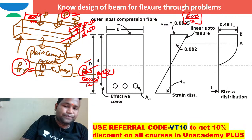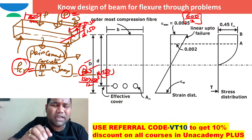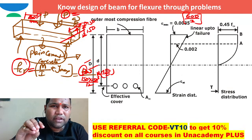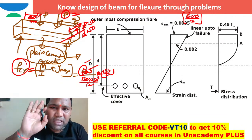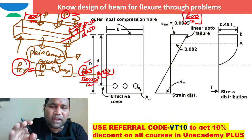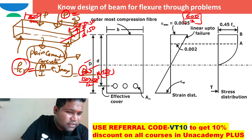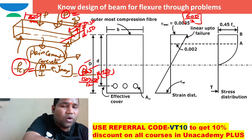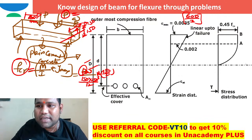Definitely, right? I hope you know how to work out that fcr, but that value is very low when compared to the compressive strength of concrete. So that is approximated as 0. That's the reason why we say concrete is weak in tension and it is not taking any tensile stresses.